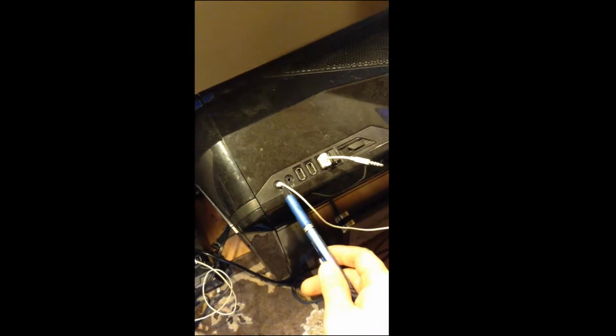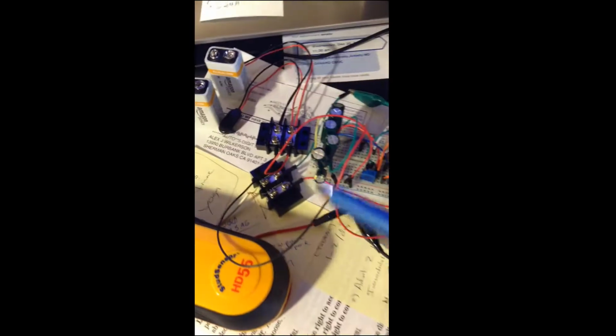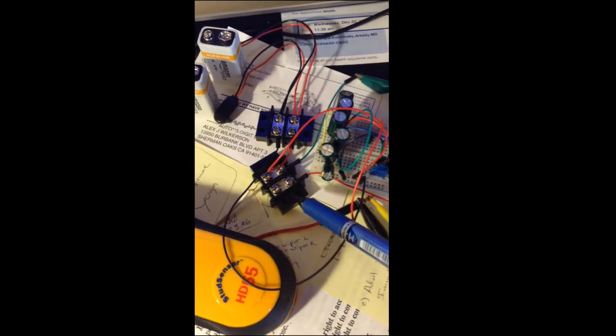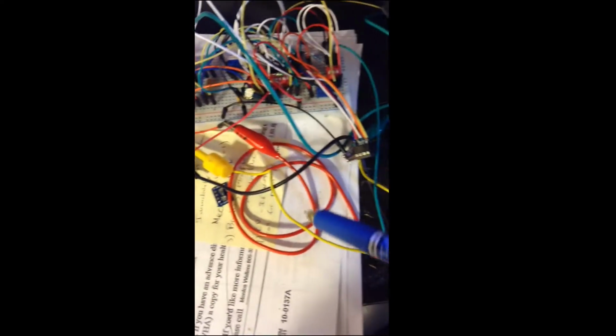The way that this system works is our input signal is coming here from the computer headphone jack. This is coming in mono, so I'm only using 1/2 of it. It goes to this terminal block here. The green one goes to the ground bus, which you see here on the breadboard, and the red goes to this alligator cable, which is going over to here and is connected to this yellow breadboard wire, which is the input of the circuit.